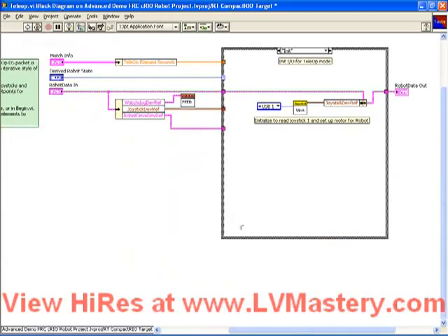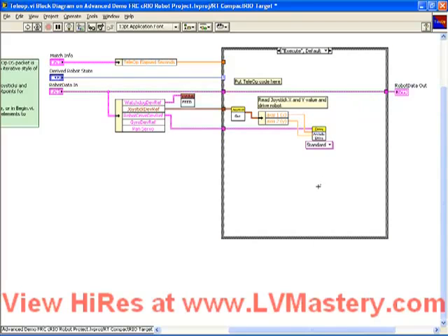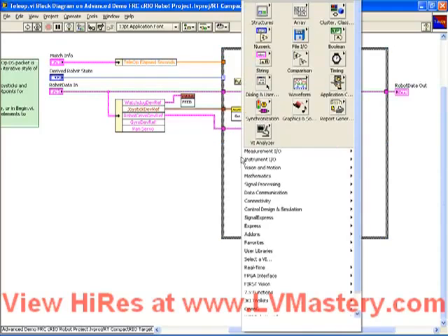So let's take a look at the block diagram again. So here's our robot data in. We just saw that on the front panel. So not surprising, if we pull this guy down now, we have available the gyro device ref and the pan servo. If we return to the execute stage, which is where we're going to make our code modifications, now we can add the same code that we added in the previous example. We want to do a gyro read.